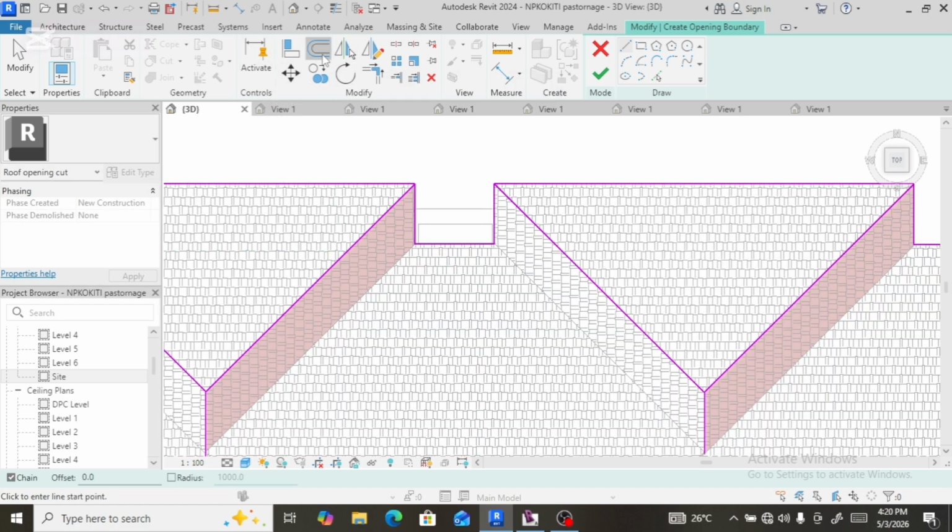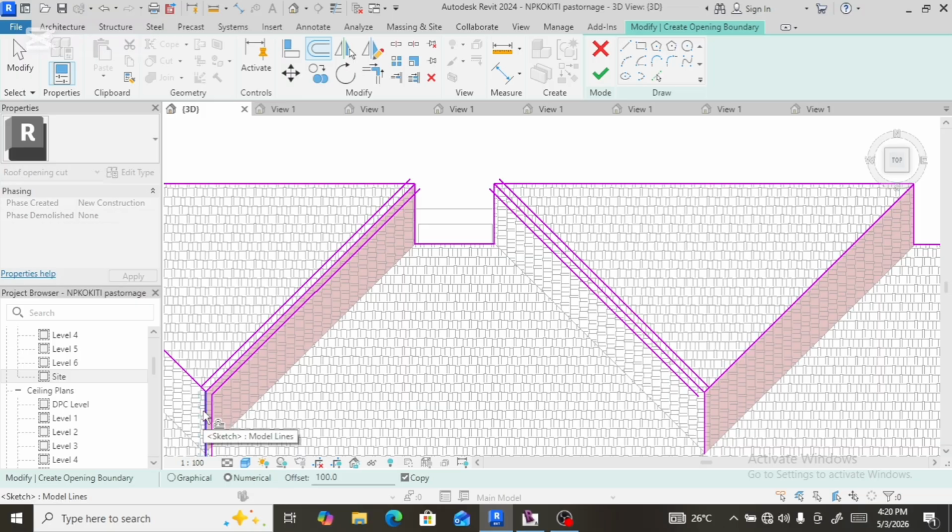Using the offset bar, you need to come down to this place. Unlike release 2024, set your offset here. This time around in 2024, I decided to use 100 millimeter for my ridge cap expansion. I'm doing this quickly, just the ridge cap area.